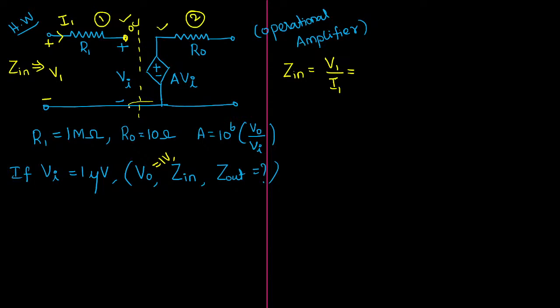You may have the other part, but do you remember what I have told you? When your circuit is not closed, then you cannot pass any current through the circuit. Can you pass any current here? No. Of course, voltage will be transferred here because this is an open circuited line. Since it is the open circuited line, if I inject any current here, there will be no return path because here itself it is open circuited. Open circuited resistance will be infinity. Obviously, current will become 0 ampere. So there is no current flow in this path. You understand, no? So let us see.